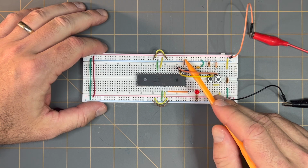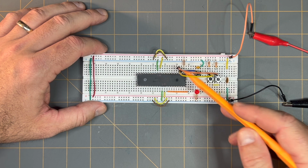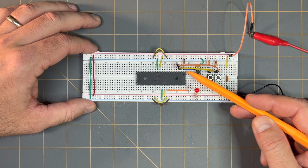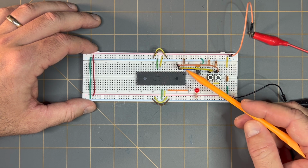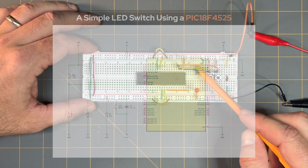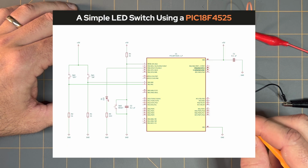So I mentioned that resistor earlier, that 1 kilo ohm resistor. This is resistor R4 from the schematic diagram. Like I said before, this is pin 1 that we're connecting that 1 kilo ohm resistor to. That's resistor R4. This is going to be our master clear pin, and that blue jumper wire goes to this push button switch, which is switch 3 on the schematic diagram, and then this 0.1 microfarad capacitor is capacitor C2 as referenced on the schematic diagram.